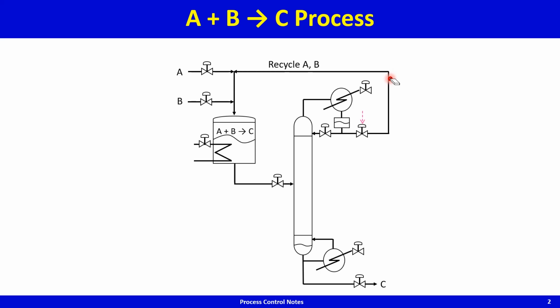So now let's see, at the very basic level we have 9 control valves, 6 on the column and 3 elsewhere. So that's 9 control valves. So the control degrees of freedom is 9, and let's say the operator specifies the position of all these 9 valves. That's the way we are running the process. Well, that's not a great way of running the process. All of us would agree with that, and that's because